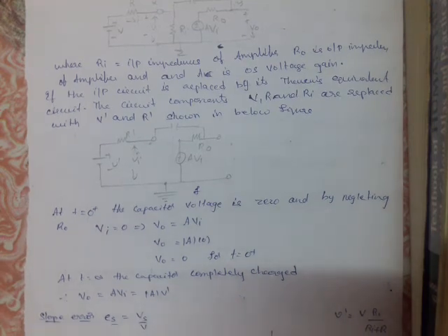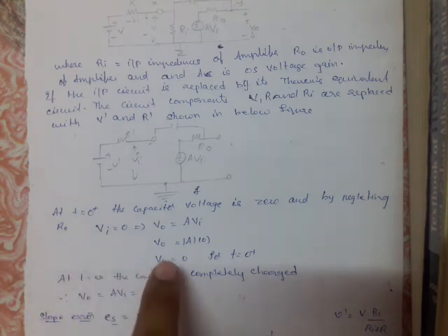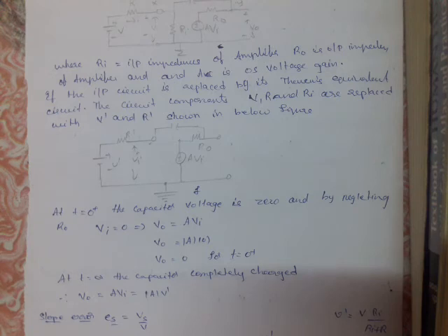So the difference we understand here is, when we consider t is equal to 0, we get output voltage equal to 0, but at the infinity condition we consider V naught equal to V in. So whenever you take any voltage amplifier or amplified circuit, we have to keep the maximum time constant value in it, then only we will get a large output voltage.